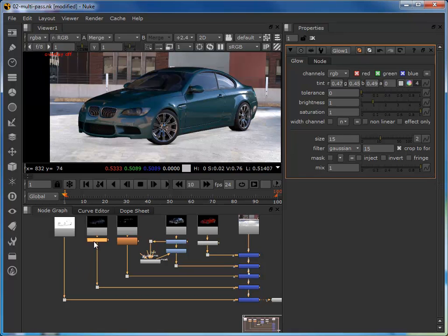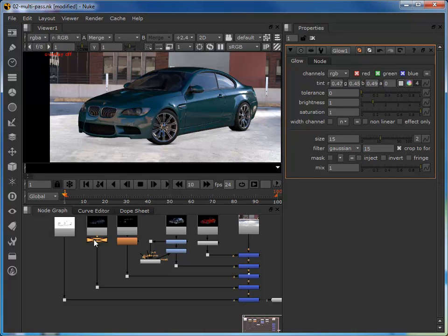And if we toggle the glow on and off now, you can see that that's much more subtle. If I want to reduce it a little bit more, again, I could mix down the effect, maybe to 0.9. Let's look at it now. And you see it's much more subtle, having a much more subtle cast. But again, the tint is much more relevant to this background. It's tying in a little bit more with this background. So that's the advantage of using the tint to mix the glow that's being applied onto the specular. So on to our final pass, which is the ambient occlusion.